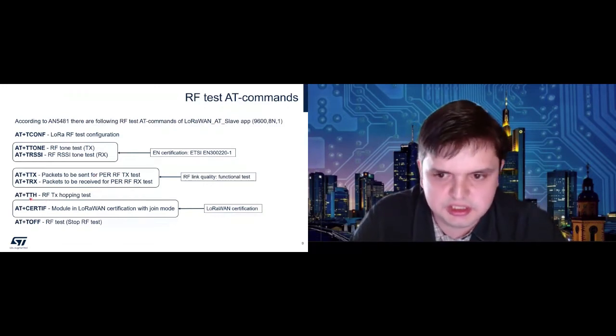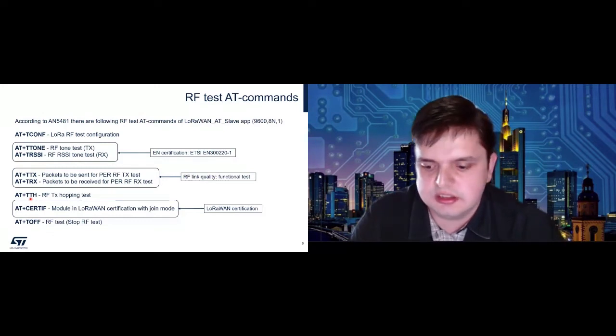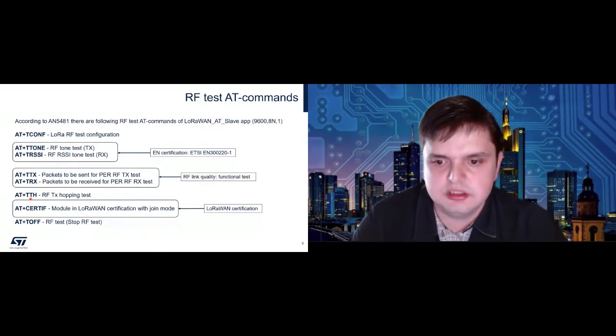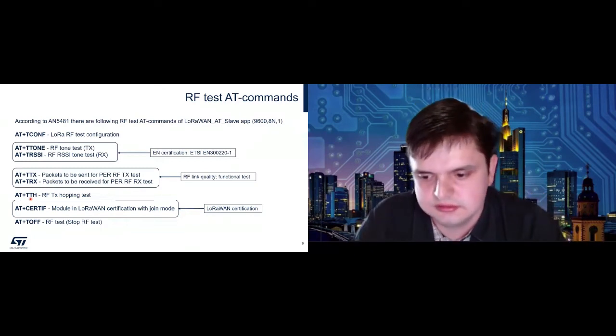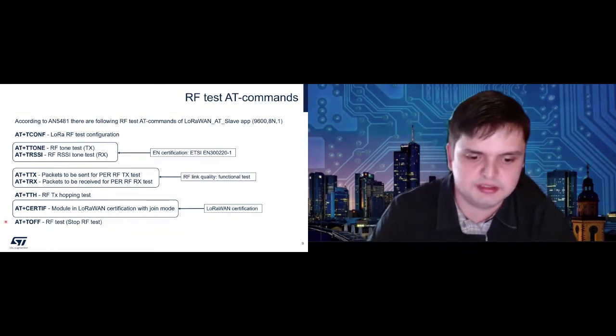So basically, it activates the state machine inside the stack to trigger certification mode, and LoRaWAN certification can be done, and eventually, based on this test, you receive your LoRa Alliance certification. And then any test can be stopped at any time by AT+TOFF, which simply disables everything.